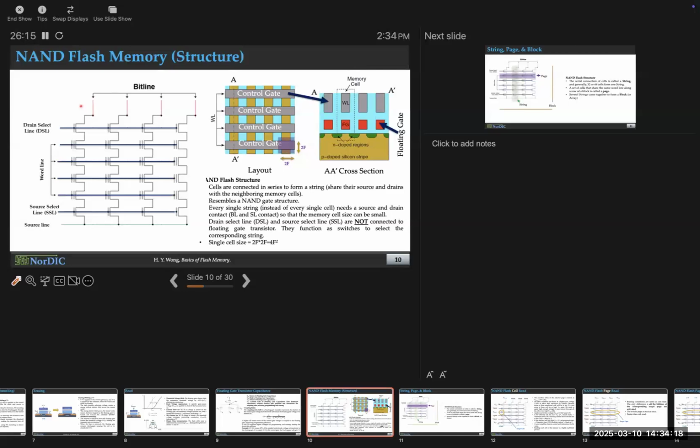Okay, number 2. Have you seen a NOR gate? What happens to the NMOS branch? Are they in series or parallel? 2-input, parallel. 3-input, 4-input, doesn't matter how many inputs. It's always in parallel. Exactly that for flash memory. That has to deal with the array structure. When you design the array of a flash memory, and there are reasons, I will explain the reason in great detail. But for the time being, keep that in mind.